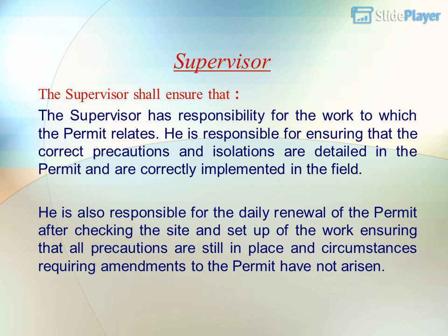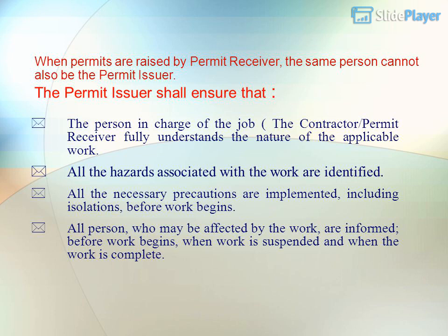Supervisor. The supervisor has responsibility for the work to which the permit relates. He is responsible for ensuring that the correct precautions and isolations are detailed in the permit and are correctly implemented in the field. He is also responsible for the daily renewal of the permit after checking the site and setup of the work, ensuring that all precautions are still in place and circumstances requiring amendments to the permit have not arisen. All the hazards associated with the work are identified.